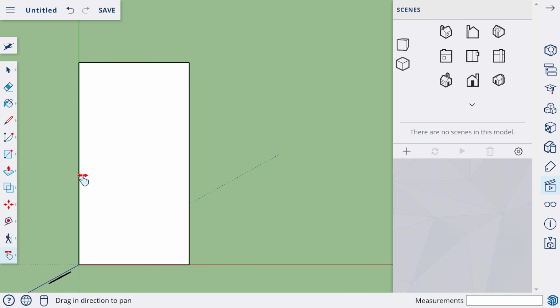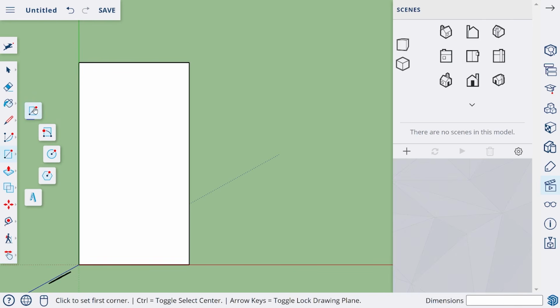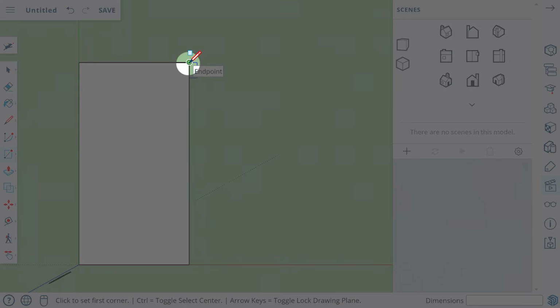So this vertical rectangle is going to be the main living area of the space. And then to the right, we'll create more of the private areas like the bathroom and some of the bedrooms. So we need an entryway into this space. So let's use the rectangle tool once again. We'll click on the rectangle tool, click to make it active.